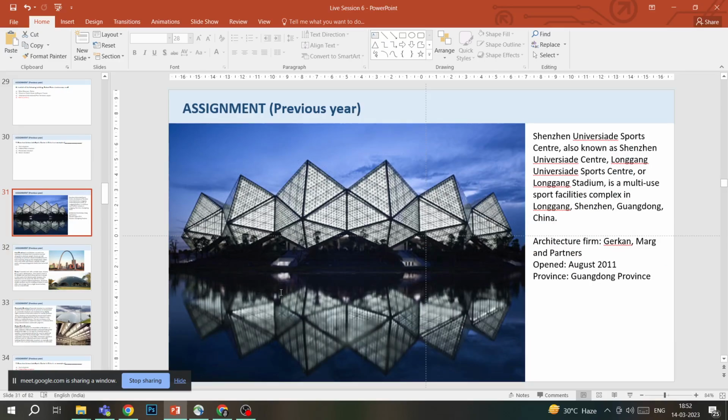It's a different kind of folded plate structure, as we have seen in the examples where we usually see a chevron pattern in spans. But this is a folded plate structure. Why? Because there is a flat surface which is joined at an angle to another surface along its edge. That's why it's a folded plate structure.